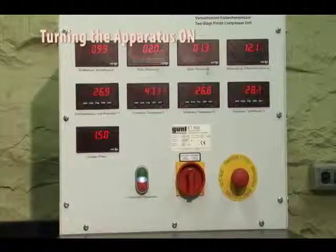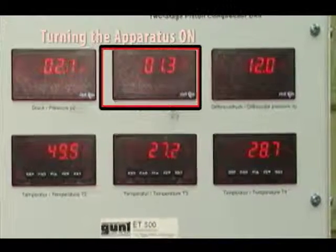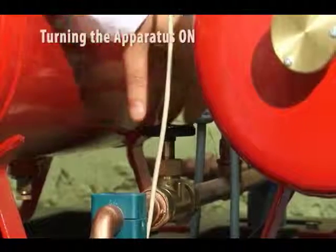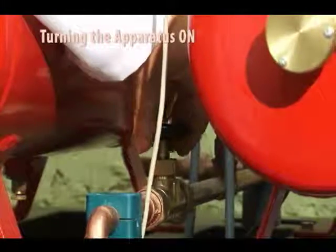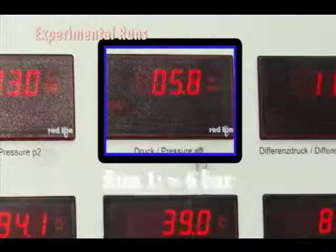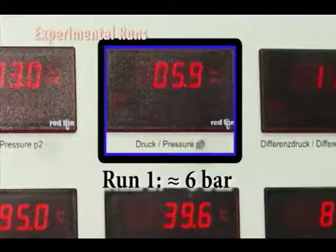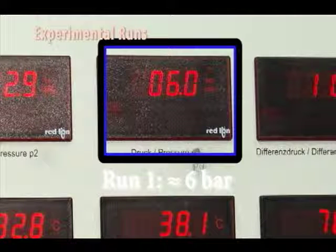Allow the compressor to run for several minutes until the pressure in the pressure vessel of the second stage, P3, has reached a steady value. Using the throttle valve, regulate the pressure P3 to the desired value, between 6 and 12 bars. Please note that the system is set to run an emergency stop when the pressure reaches 12.6 bars in the pressure vessel of the second stage.